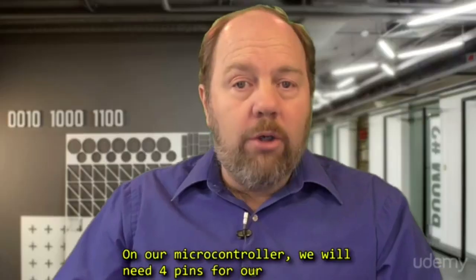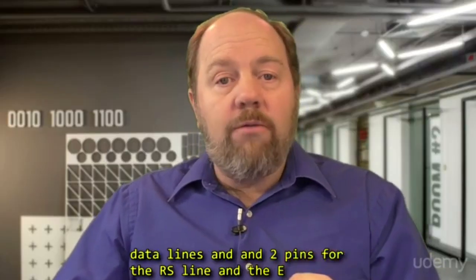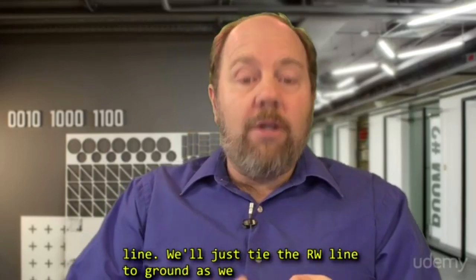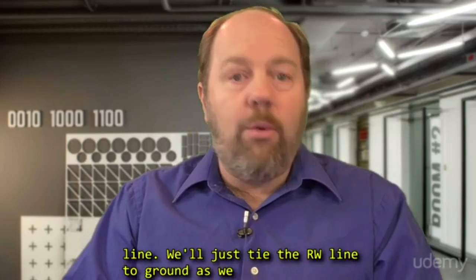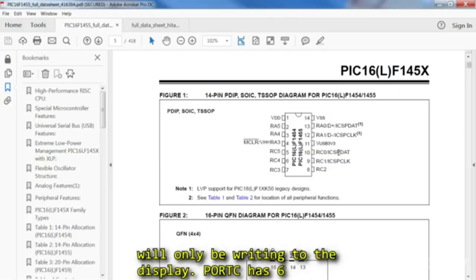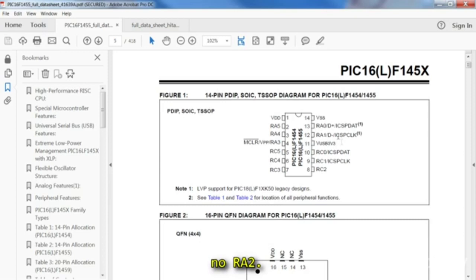On our microcontroller, we will need 4 pins for data lines and 2 pins for the RS line and the E line. We'll just tie the RW line to ground, as we will only be writing to the display. Now, port C has 6 pins we can use. Port A has 5. Notice there is no RA2.